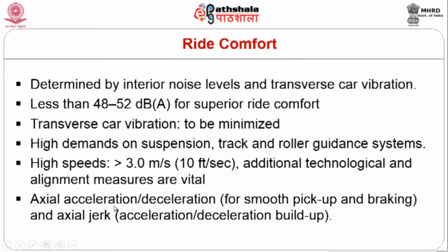Axial acceleration and deceleration are very important, and they need to be very smooth in terms of picking up speed and in terms of the braking system to bring down the speed. When the elevator car stops at a particular floor, the jerk factor also has to be taken into account, and we need to bring in an almost smooth landing experience for the occupant within the car.